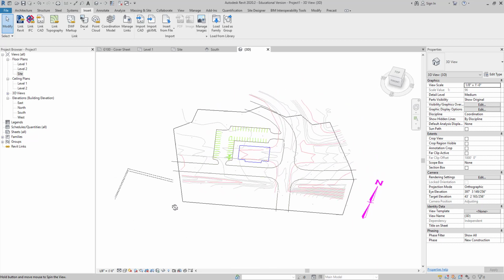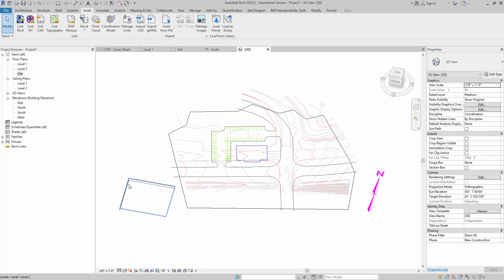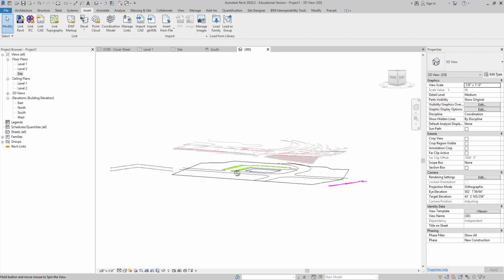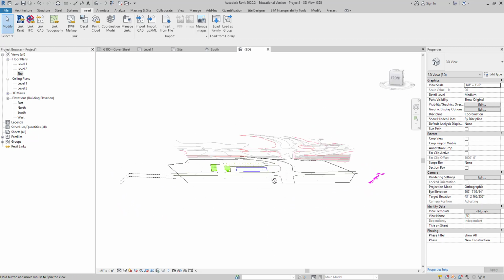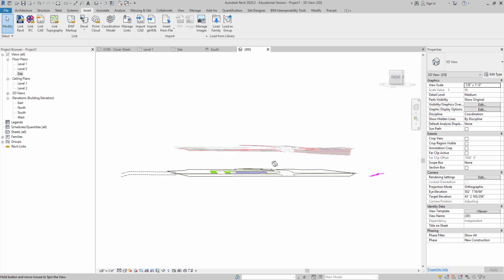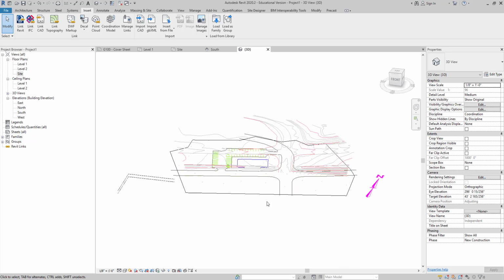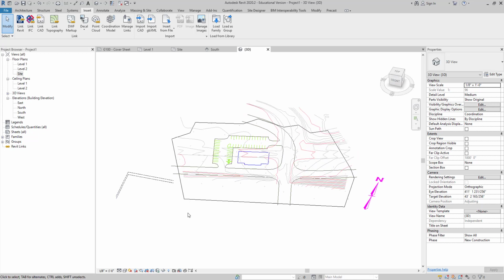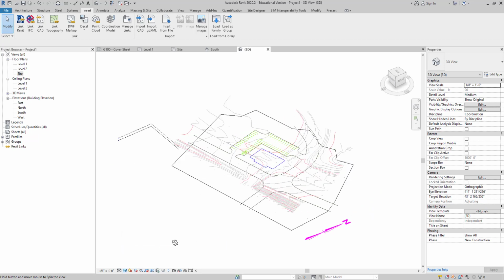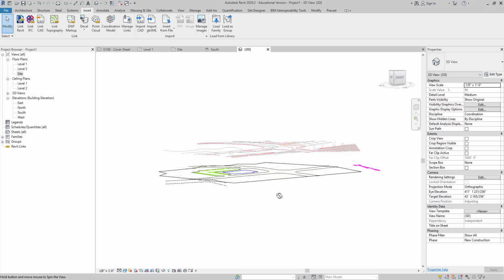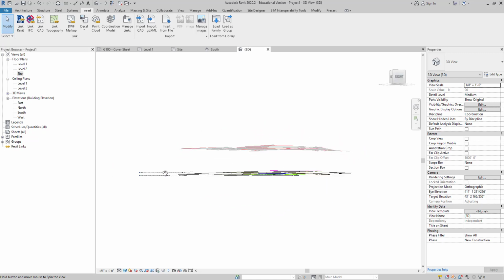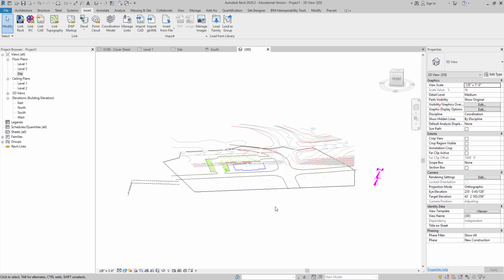Okay, these two shapes over here are our levels from Revit, and everything else on the screen is straight out of AutoCAD. We can see that some of those objects are flat, and the topography is up at the top, and it's actually at the correct elevation. So I'm going to turn this view to a shaded view, because I want to demonstrate that there's currently no surface. I feel sort of like the magician that says, look carefully, I've got nothing up my sleeves. There's no surface there now.